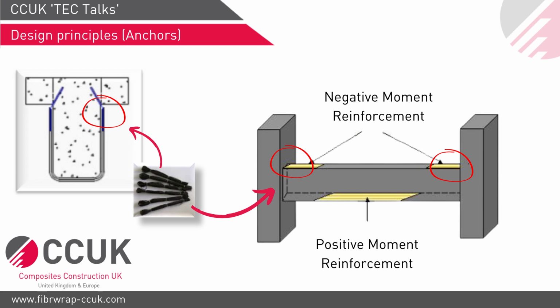I see. Yeah, so we need to have some sort of anchorage detail there, or development length, that could be done using carbon fiber anchors, or it could be done by wrapping the FRP up onto the column, then put additional hoop around it. But there has to be some sort of detailing there, and engineers should ask for these kind of detailing from FRP designers.